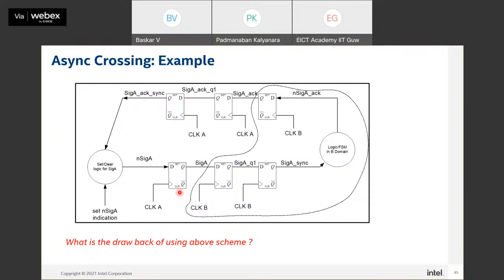Now, what is the biggest drawback in this scheme? The latency. The user has to send the information, then wait for B to give an ACK. Overall, this might take 7 clock cycles, typically with respect to this example. Today, to meet our end customer demands, how fast you process the data is one of the unique selling points.